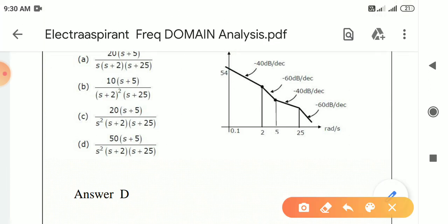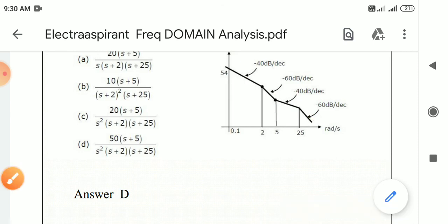The first step: as per the given Bode plot, it is very clear that in the magnitude plot there are 4 line segments, 1, 2, 3 and 4, which indicates there will be 4 s terms, then a constant term in the transfer function. So first we can identify the corner frequencies, and the poles and zeros locations.